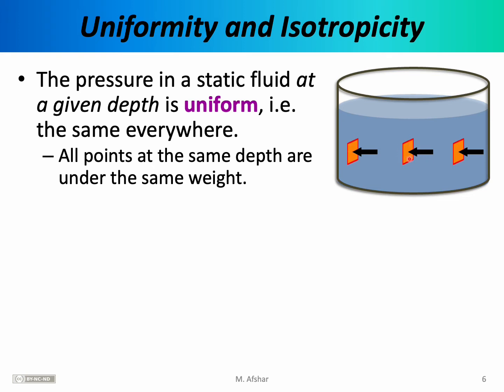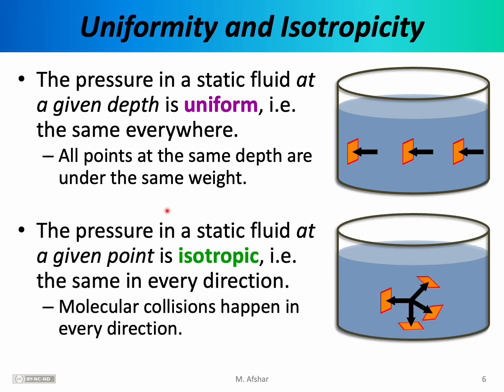So whether you're in the middle of the container or closer to the walls, so long as the depth is the same, the pressure is the same. The second important fact is that the pressure in a static fluid at a given depth is isotropic, meaning that it is the same in every direction. Remember that we're talking about fluids here, and molecules in a fluid are free to move in every direction. So molecules at this point here inside the fluid are certainly moving down, but they could also be moving to the left or to the right, upwards or diagonally.